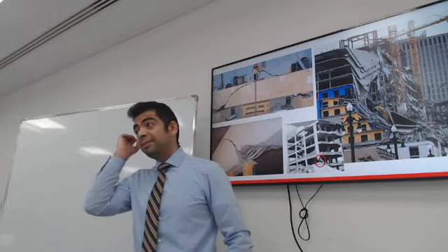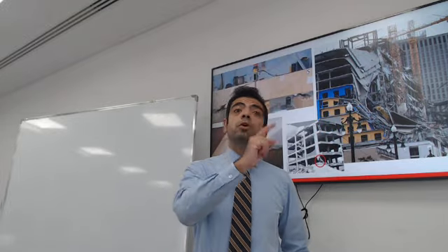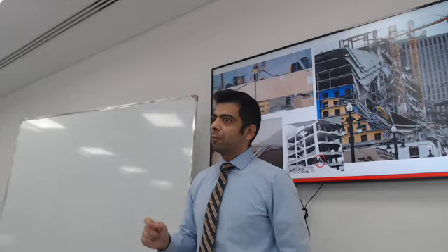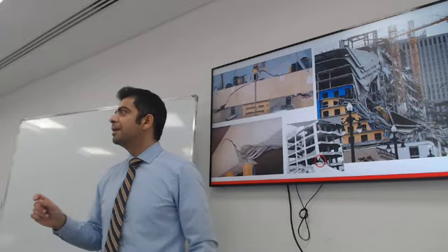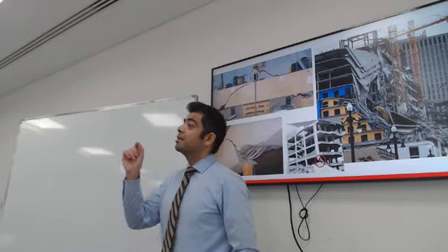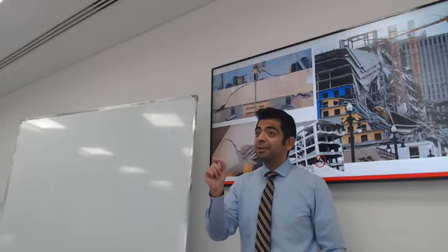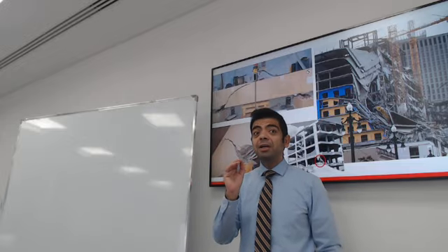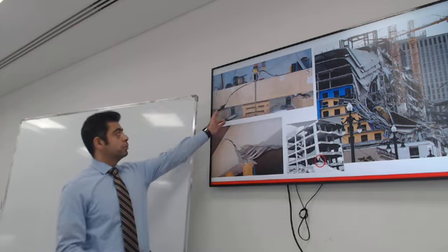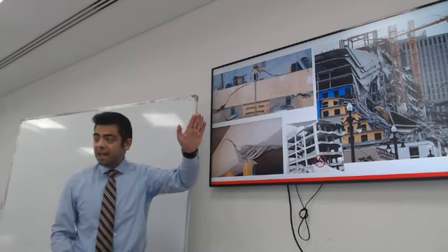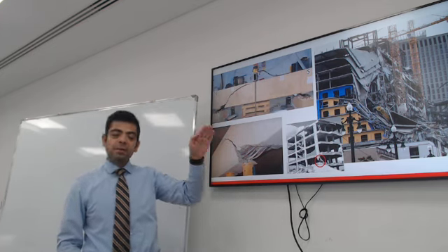How can you tell visibly when you look at a beam that is suffering from a lot of shear and is about to fail? Yes, the shear crack has a very distinctive characteristic. It is very close to the support and it has an angle. We will talk about this angle today.